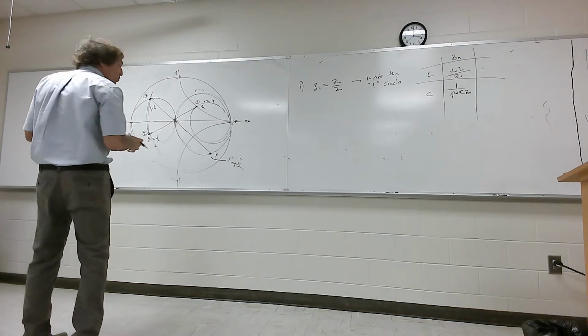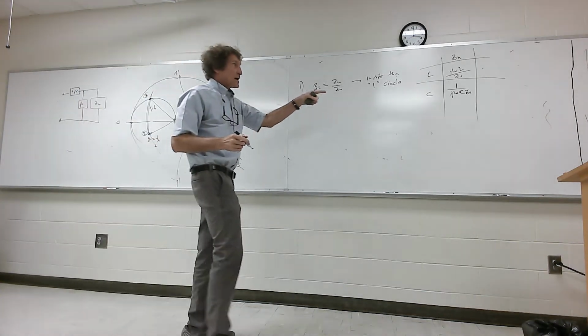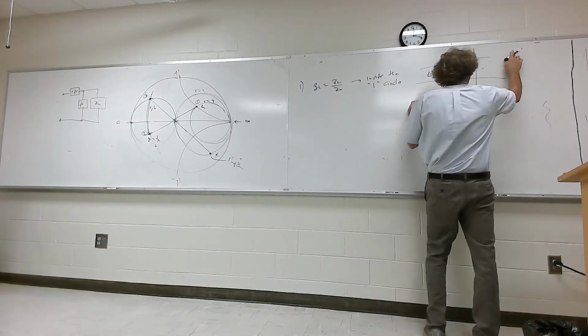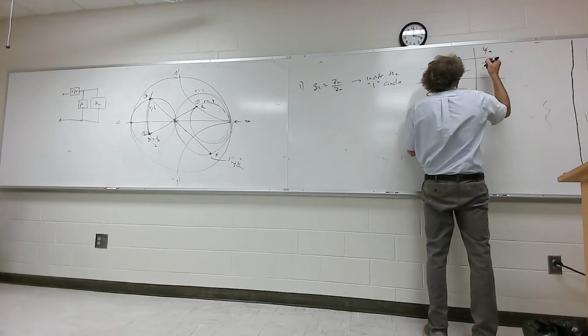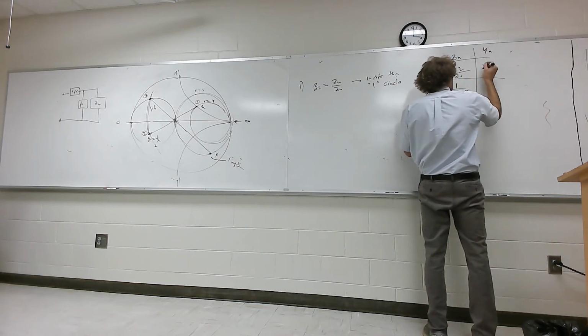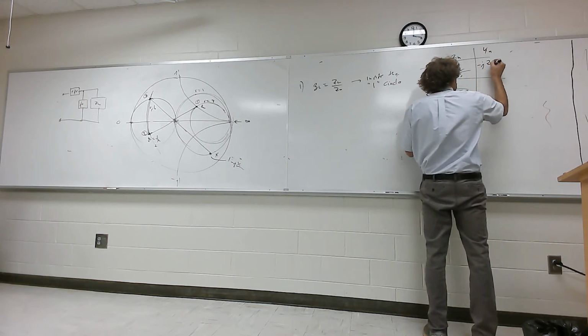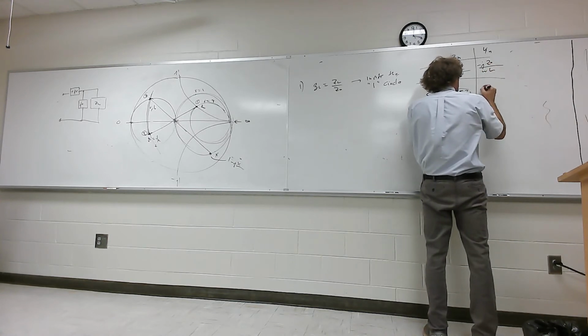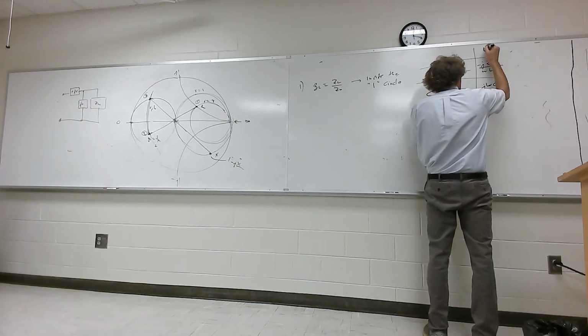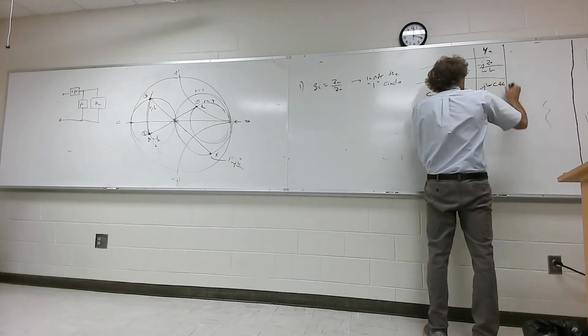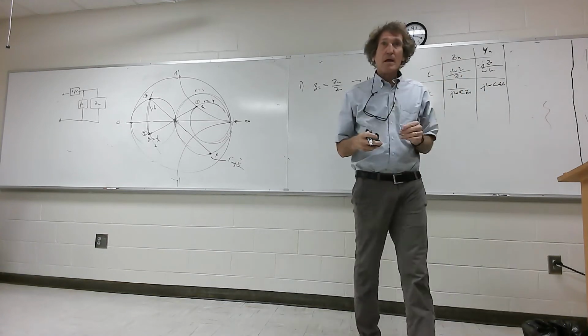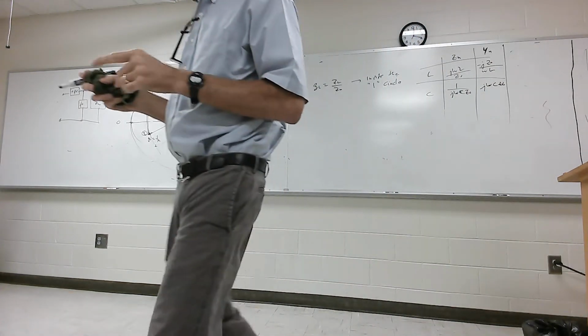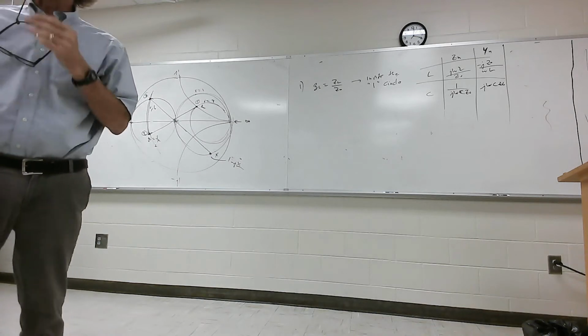Now, that's normalized impedances. The normalized admittances are 1 over this. So for this one it would be minus J Z naught over omega L. For this one, it's going to be simply J omega C times Z naught. These are the normalized admittances. You with me? You'll notice they're functions of frequency as well as the values of the elements, C and L.